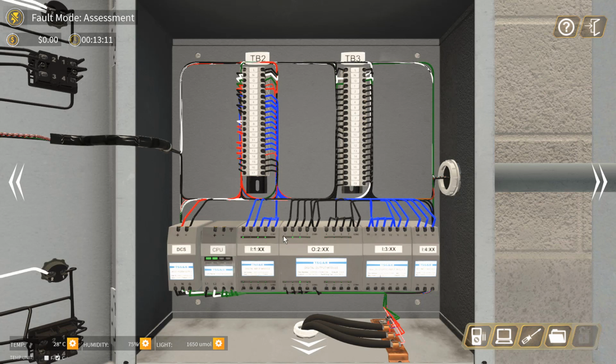So when we see this kind of thing, our intention, our thinking maybe, is to straight away change the PLC output card. But hold on first, don't do so. We try to check further before we change the PLC output card or input card. The problem may be due to other circuits, may be from other circuits, not from the PLC card itself.